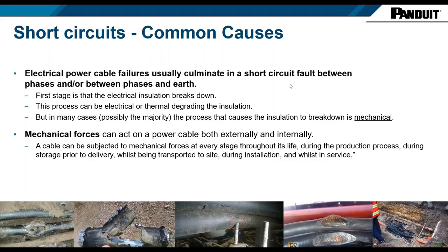The middle example is taken from a rail installation in the UK. So the guys were lifting live cables, and what they were doing was changing some cleats. And the guy who was moving the cable thought he'd put the cable up on that piece of strut, which you can just see at the bottom of the image, but he'd actually placed the cable on that threaded studding.